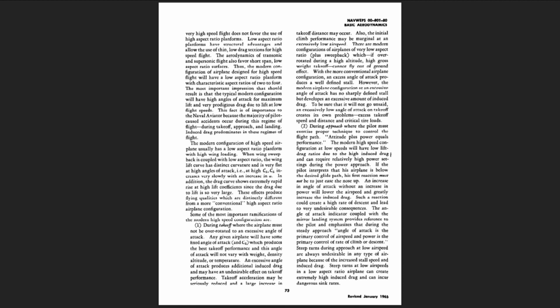2. During approaches the pilot must exercise proper technique to control the flight path. Attitude plus power equals performance. The modern high-speed configuration at low speeds will have low lift-drag ratios due to the high induced drag and can require relatively high power settings during the power approach. If the pilot perceives that his airplane is below the desired glide path, his first reaction must not be to just ease the nose up. An increase in angle of attack without an increase in power will lower the airspeed and greatly increase the induced drag. Such a reaction could create a high rate of descent and lead to very undesirable consequences.